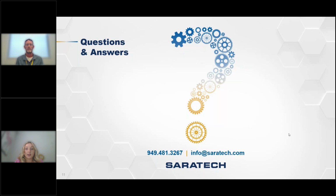Perfect. And then we just had another question come in. Will you need a separate license to build an MTK or ISV in NX? So MTKs are post builder, machine builder, or I should say simulation kits. ISV is post configurator, machine configurator, and you have the capability out of the box to build post processors. You just don't have the capability to go into the TCL DEF editors. That requires the advanced license.